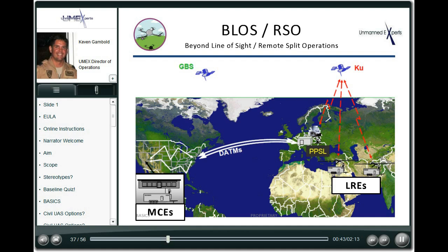But there's another way to do that, and that is by what's known as data or radio relay, where you can put a UAV with the right capabilities and antennas in the middle between the one that you want to fly and operate and where your ground control station is. Effectively extending the radar line of sight by using another UAV, and the Hunter MQ-5 does that.